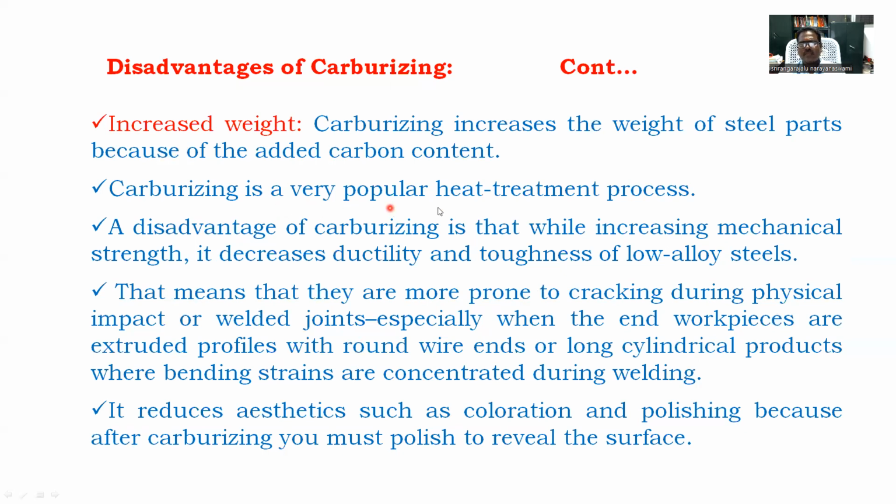Carburizing is a very popular heat treatment process. A disadvantage of carburizing is that while increasing mechanical strength, it decreases ductility and toughness of low alloy steels.